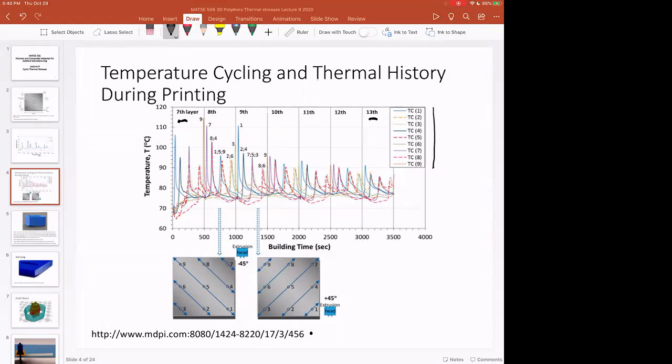And so we're used to analyzing components for cyclic thermal stress in use, but this is analyzing components for cyclic thermal stresses as they're being built, or as you're creating all these additive interfaces, because remember, this is material extrusion AM.